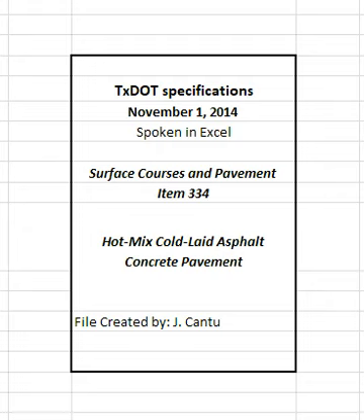Cease production if 3 consecutive tests indicate that the material produced exceeds the tolerances shown in Table 6 for any individual sieve or laboratory molded density until corrective actions are taken and the results approved. Cease production if 2 consecutive tests indicate that the asphalt binder content tolerances shown in Table 6 are exceeded until corrective actions are taken and the results approved. Cease production if the beam stability shown in Table 5 is not met for 3 consecutive tests until corrective actions are taken and the results approved. Table 6. Operational tolerances. See table in specifications.